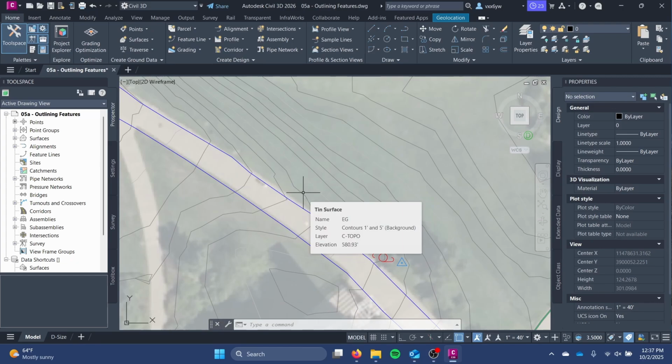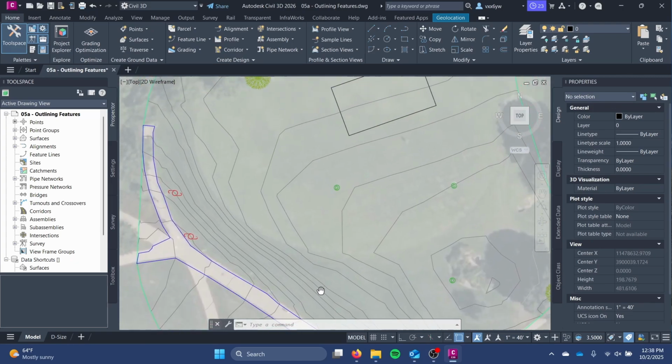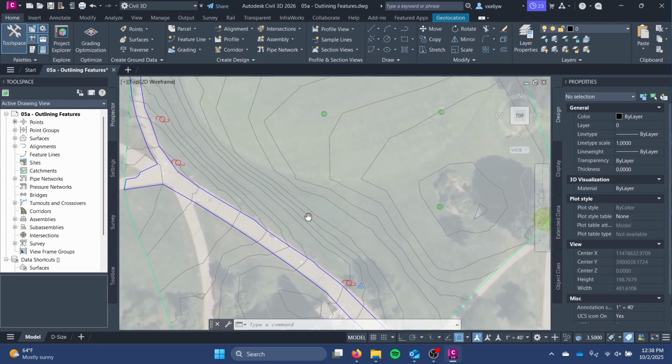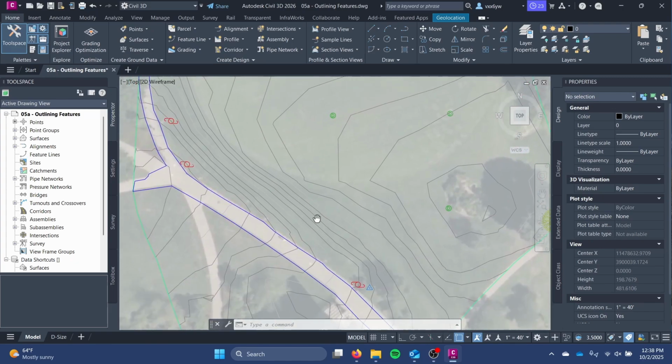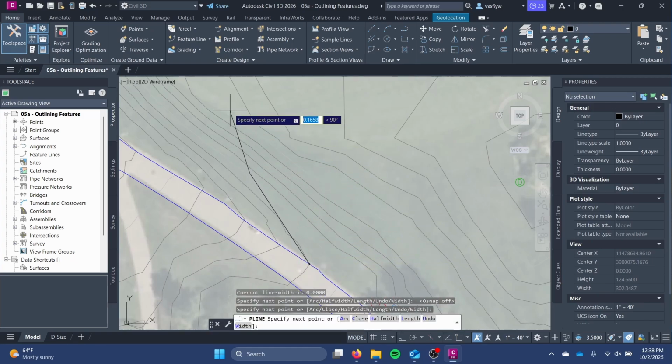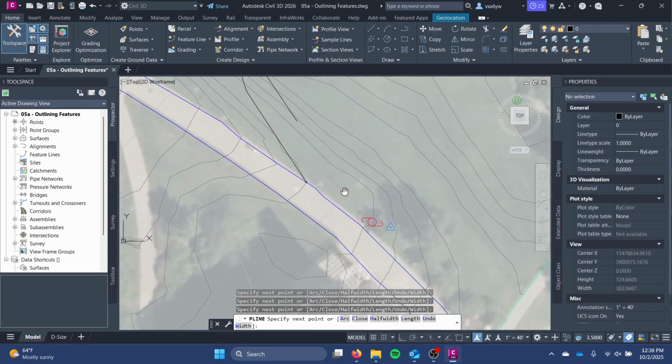Now, I'm going to do this using a 2D polyline. I'm also going to keep my object snapping off, otherwise it's going to probably mess up a lot of my design. And this is going to be a little bit interesting the way I do this. I want my sidewalk to be of a constant width, for example, 6 feet. So I could go here and actually use my polylines and make my whole object and then make sure it's exactly 6 feet wide, but that's really hard to do.